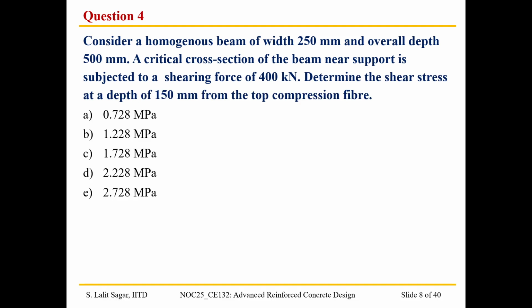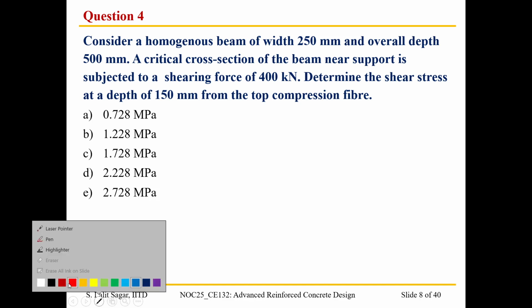So consider a homogeneous beam of width 250 mm and overall depth 500 mm. The critical cross-section of the beam is subjected to a shear force of 400 kilonewton. Determine the shear stress at a depth of 150 mm from the top compression fiber. Kindly take a few minutes and let me know what is the correct response. I'm going to start solving the problem simultaneously with you.